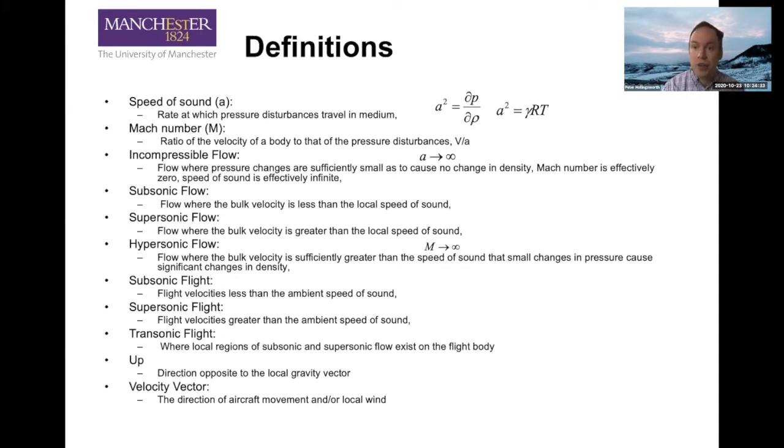As A goes to infinity, we say that the medium, the air, the water, the fluid, becomes incompressible. That means that information, pressure information, basically travels instantly from one side to the other. If A goes to 0, it becomes infinitely compressible, and that's what we represent as effectively hypersonic flow. So incompressible could also be called hyposonic flow, as in so much slower than the speed of sound, we don't really care about it. Mach number is relatively easy.